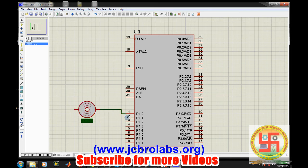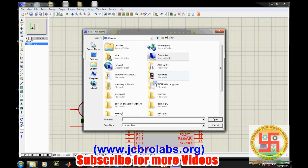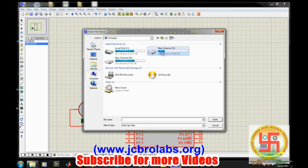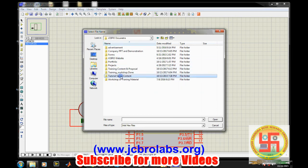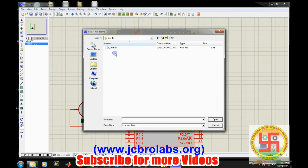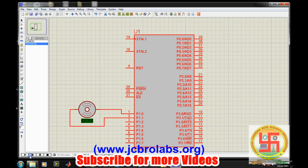So this is the beauty of Proteus. We don't need to connect any driver or ground and other supplies in order to make it run. So simply now let's provide the hex file which we have generated. Lesson 10, and this is the hex file, and okay, so let's run it. For some time it is running in one direction, and for another time it's running in another direction.